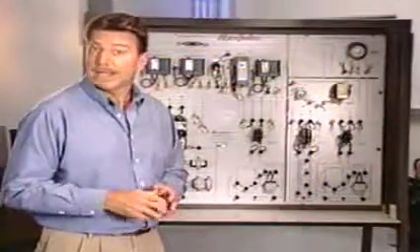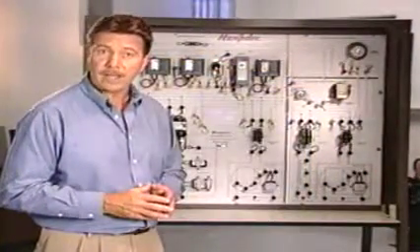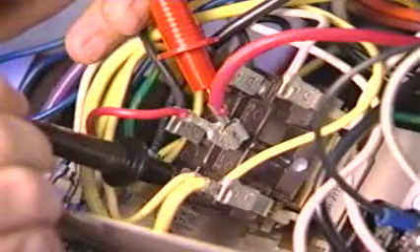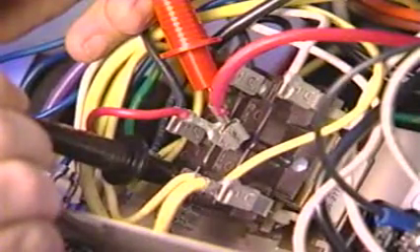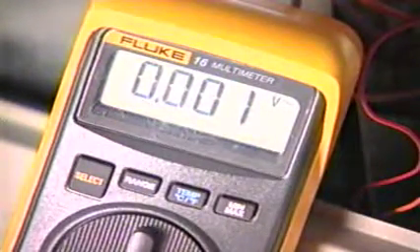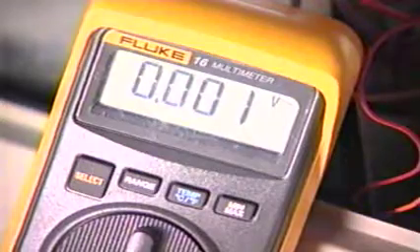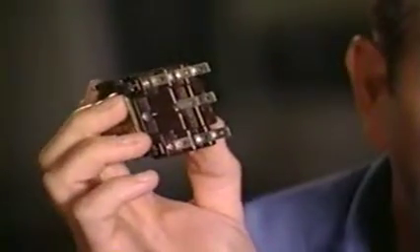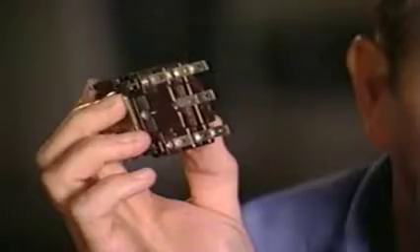A voltmeter can also be used to check the contacts of a relay that is in an energized circuit. When the relay coil is energized, the voltage reading should be 0 across a set of normally open contacts, as these contacts should now be in the closed position. Relays are typically throwaway devices, so if the relay malfunctions, it's best to replace the entire device.